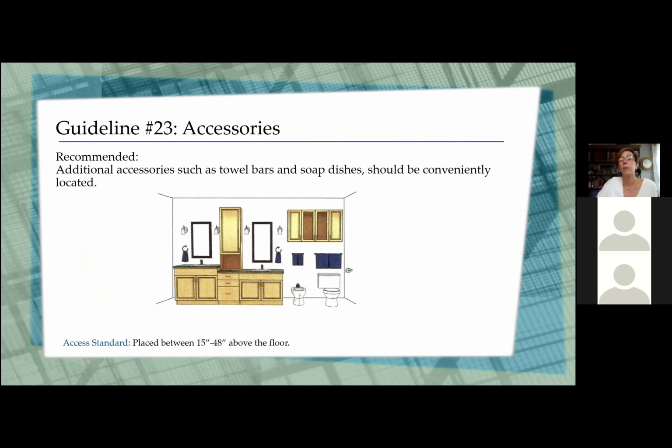Other things, towel bars, soap dishes, they're really user initiated, to make sure that you've got enough in there. A lot of questions I will typically ask a client is, do you like to hang the towel over a bar, or are you a hook person? A lot of that will drive my designs in terms of the space needed, and do we need to plan for those 24-inch or 18-inch towel bars, or will hooks just suffice? If you've got somebody using the bathroom that needs access, or that is in a chair, just make sure that you're, again, sticking between that 15 and 48 inches above the floor.